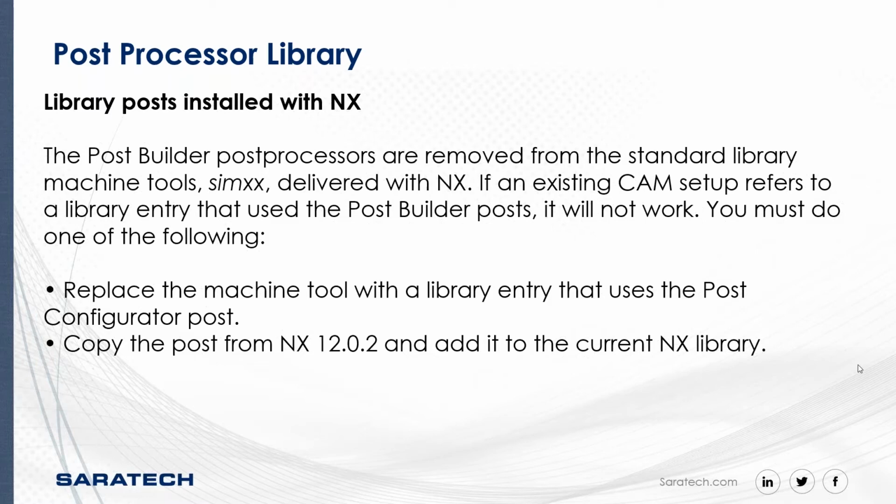So now they came out with Post Configurator. It's been out for a while now, and it's very robust. And moving forward, I would always start with Post Configurator. But we are always going to have PostBuilder to look at, modify, and change old post processors that were built pre-Post Configurator. With this version, they've removed all the PostBuilder post processors from the standard tool library.